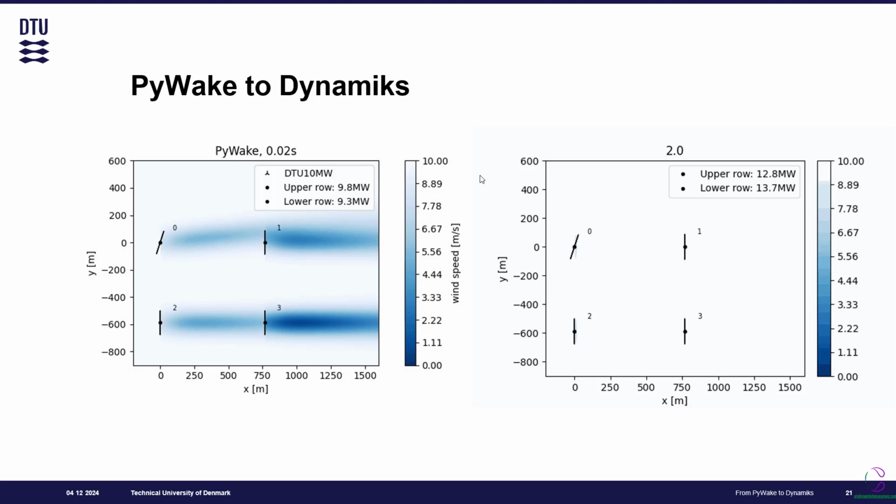Not all the time do you have reduction of wind speed at the wake, which is how Dynamiks is a better option than PyWake, because it models it in real time, how it happens in real life, more than PyWake does. PyWake is more static, it just picks one model and follows that model all the way to the end.